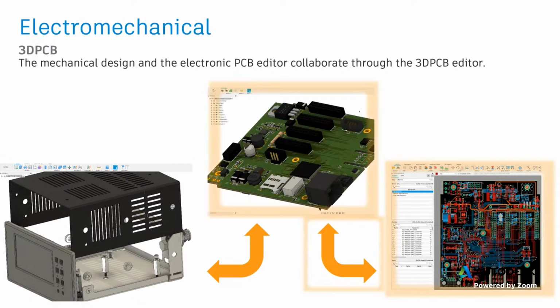First of all, between the circuit board, the PCB, and the 3D PCB, there's 100% back and forth annotation. So changes done to the PCB will affect the 3D. Now, there are some modifications that could be done in the 3D PCB. For example, board outline changes or moving components could be done in the 3D PCB. Well, you know what? That will affect the circuit board as well. So you have a back and forth annotation.